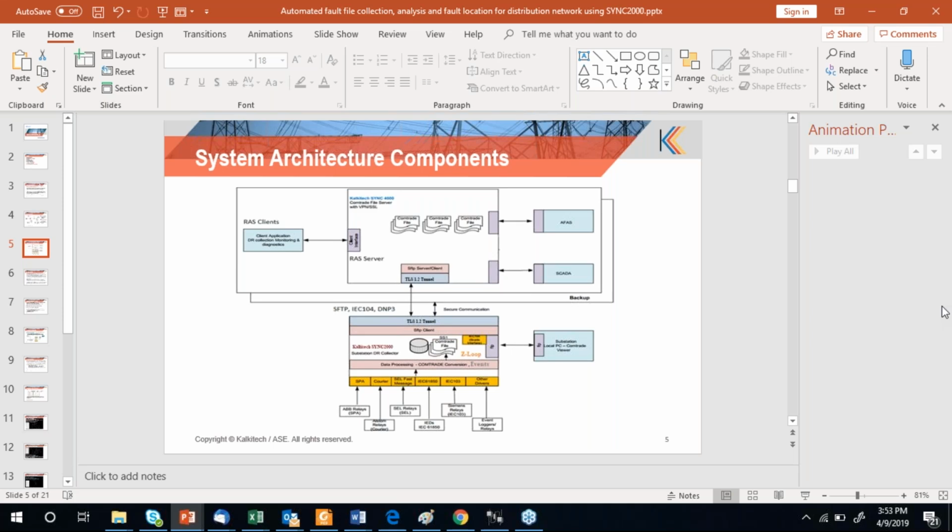So whenever we propose this, people prefer the new things, 61850, let's get it automatically, but other mapping is a bit tedious, because for every event there needs to be a description, and the values and other descriptions also need to be provided. So the answer is, for the automatic collection we only have 61850. For other protocols, though we collect, the mapping is needed to make it a user-understandable format.